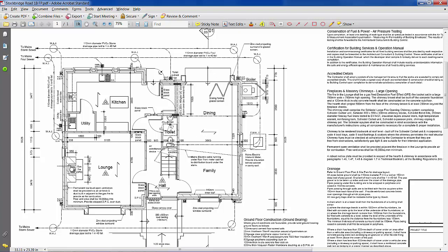so you just need to clearly indicate what those different things are. Also on the plan there is this hatch or dashed area in front of the toilet, so you need to clearly indicate in that case that you have a clear area of 900 by 750 in front of the toilet for the Northern Ireland building regulations.